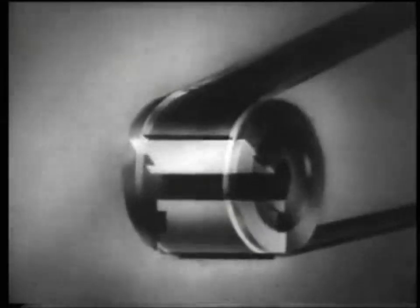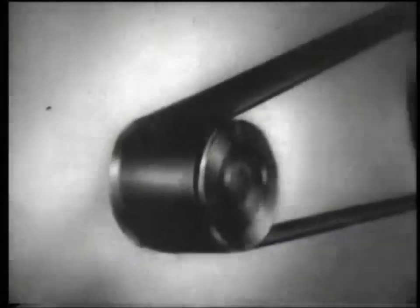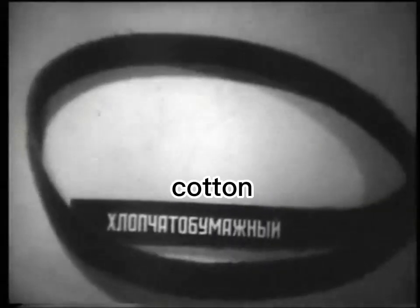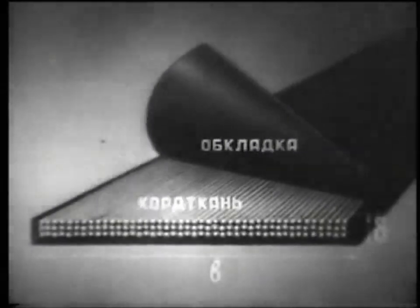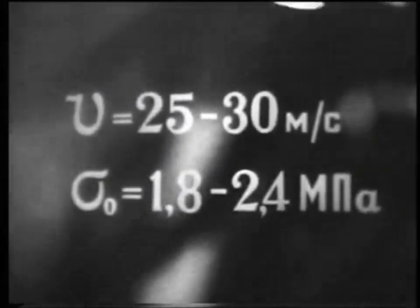In a flat belt transmission, the friction force is dispersed over the width of the belt and all elements are loaded evenly. Rubberized, leather, cotton and wool belts can be used in the transmission. The most commonly used are flat rubberized belts. These belts are used at speeds up to 25 to 30 meters per second and small stresses from pretension.